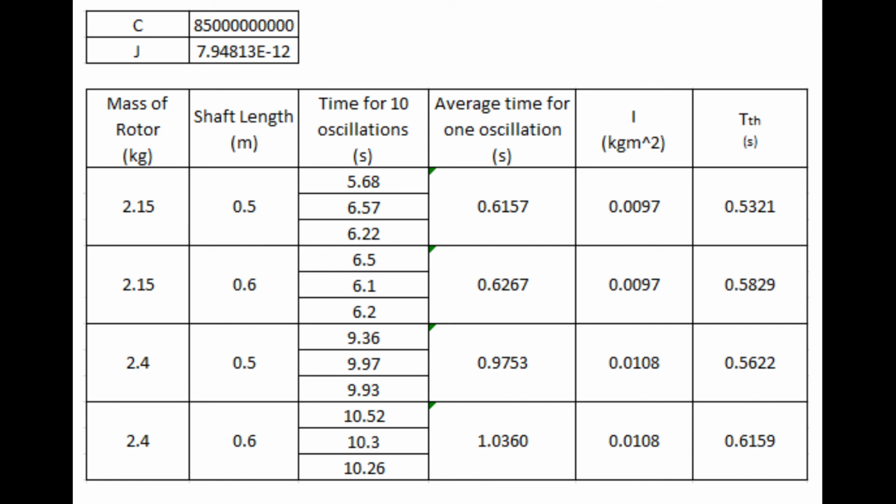Note that the initial weight of the rotor was 2.15 kgs and the extra weight that was added was 125 grams per unit, so grossly that is 250 grams when added. You can plug in all the values in the equation and calculate the theoretical value of frequency and compare it with the ones obtained practically. Now there is a difference between the theoretical and actual values obtained.